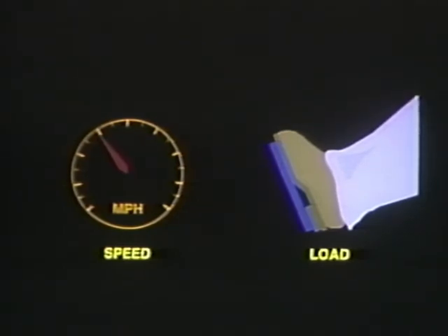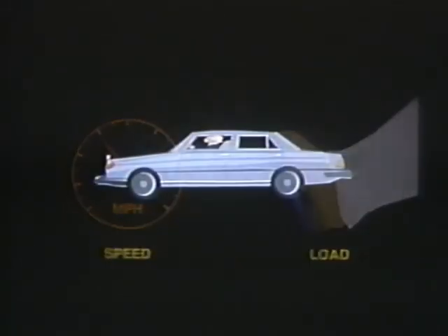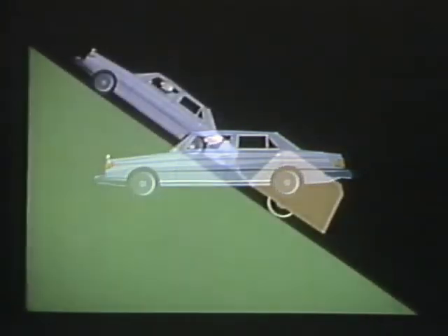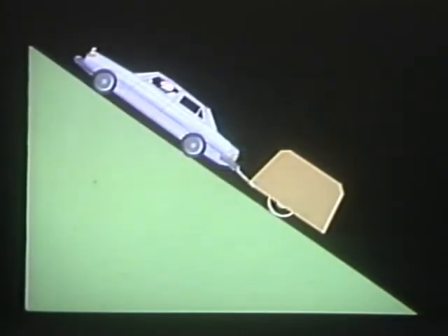But there is one other important factor regarding shifting that should be understood. We should also understand the process of controlling the firmness of the shift. For example, if the vehicle is under no load and light acceleration, the piston should apply softly and somewhat slowly so that the shift is not harsh. Whereas if the vehicle is under heavy load or fast acceleration, the piston must apply firmly and quickly. This is necessary to prevent damage to the bands and clutches.